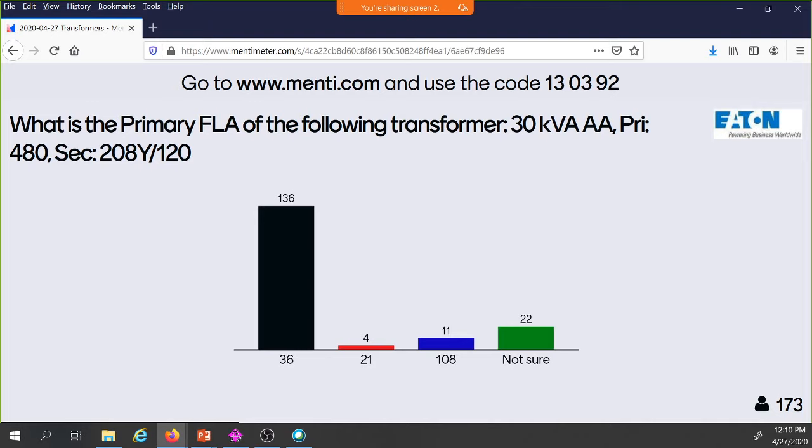At the higher kVA, doesn't it have a higher percent Z at that kVA? Kevin, no, it does not. Remember, percent impedance of that transformer is dictated by the iron core, the physical construction, and obviously the electrical performance of that. It doesn't have anything to do with the load. We get those values from short circuit testing, open circuit testing, and things of that nature on the transformer.